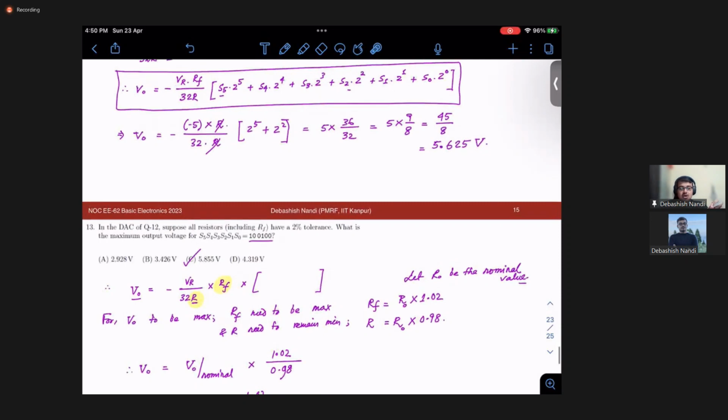In a real life scenario, if you want to buy a 1K resistance from the market and measure it, you will see that there will be plus minus 5% or 2% tolerance. Also, in the color coding of the resistance, the color bands at the end are assigned for this tolerance limit, so that resistances can have an acceptable variation about the nominal value.